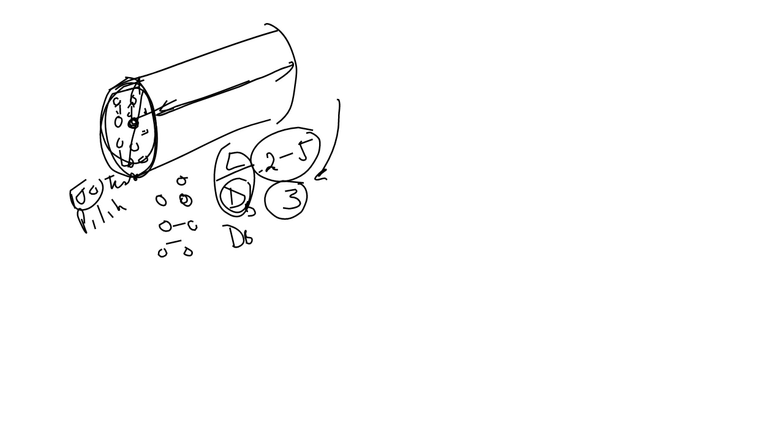This is something I look at when I evaluate your designs. Do they look pretty? Do they fall in this range? And you have control over this, because the number of tubes that you specify, their diameter, and the amount of catalyst that you must fit in there in order to bring about a certain conversion, you must decide. So, does this help? I hope.